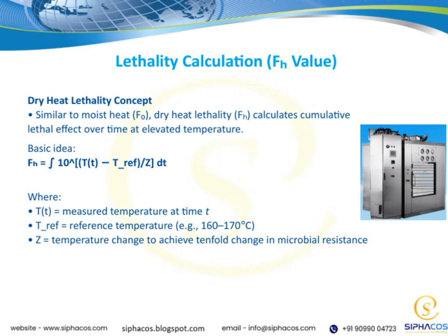Well, T is the temperature measured at any given time t, so it can vary throughout the process. Tref is our reference temperature, often in the range of 160 to 170 degrees Celsius, that we compare against. And Z is a crucial factor. It represents the temperature change needed to produce a 10-fold change in microbial resistance, essentially quantifying how sensitive microbes are